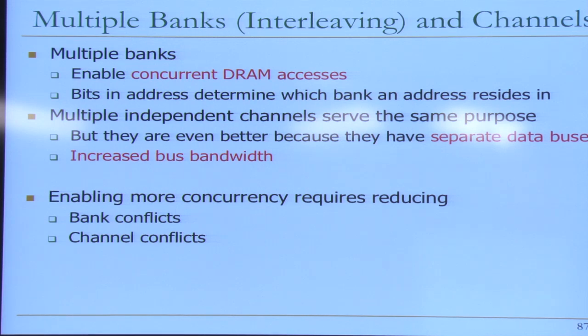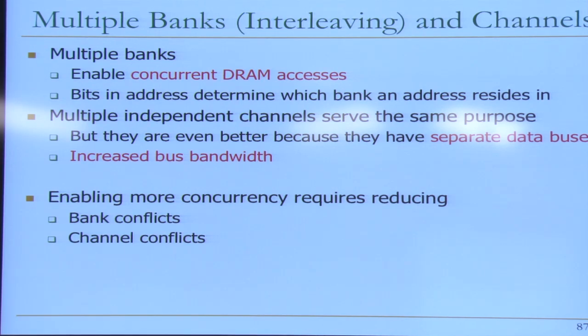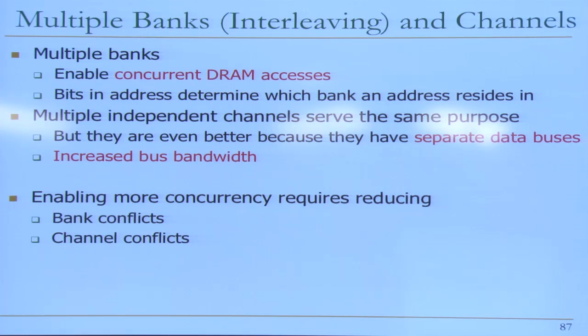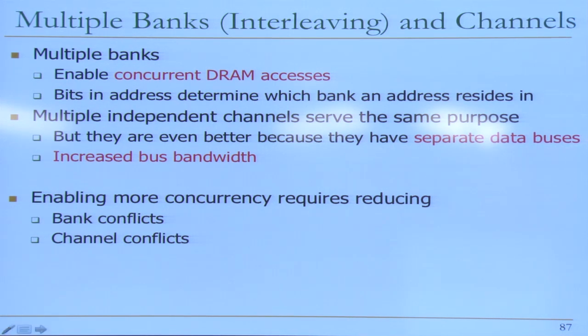Even though there are lots of lockers that are available, it somehow turns out that when I need that locker, someone else is also accessing it. That's unfortunately the nature of things. Bank conflicts happen that way too. Regardless of however many banks you may have, if the accesses happen at the same time to a single bank, well, you're out of luck. You cannot parallelize them, right? That's why a good mapping reduces the bank conflicts, but it cannot really eliminate them. So you'll have to live with it.